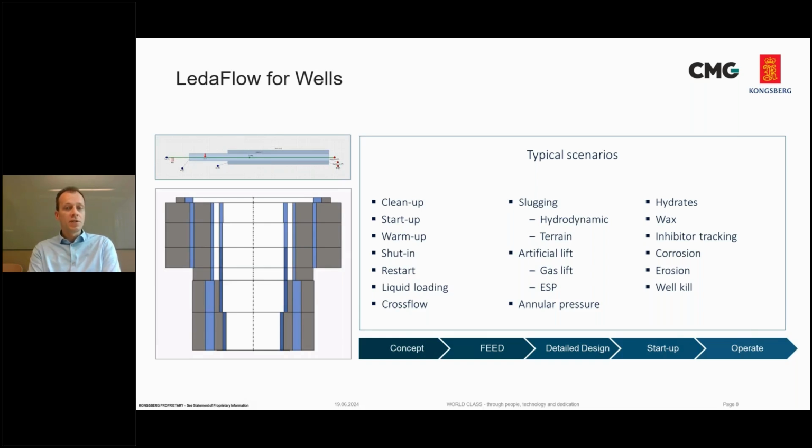So you can use that for gas lift, but also for well integrity management, looking at the pressure in the different annular spaces as the well heats up and cools down. And then you can do different scenarios like well cleanup, warm up. You can look at slugging, artificial lift, and many other flow assurance disciplines like hydrates and wax. And all of those scenarios we can simulate all the way from concept selection all the way to the operation stage.